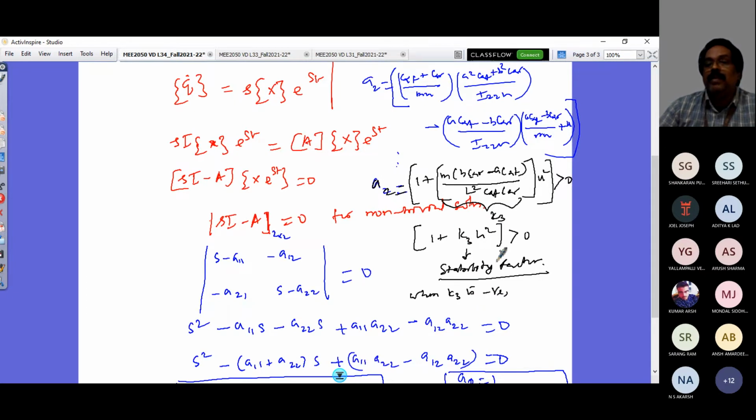You are going to make this equal to 0 and find the speed. That's going to be 1 by 1 minus K3. So this is your critical speed. At this particular speed, you see that your vehicle can no more be controlled with the steering, and it would go spinning on the yaw plane, and that's an unstable state of it.